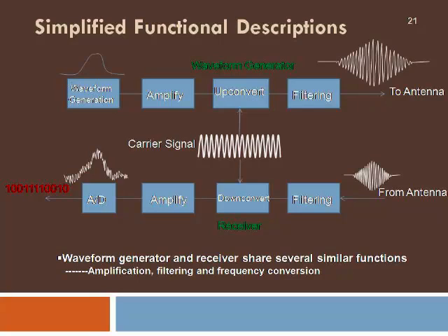So a carrier signal is separately generated for this, and after upconversion we take out the unwanted signals using filters. Then we are going to have the required pulse shape and also the required level of power within that. So it can be a simple CW signal or a pulsed signal or a Gaussian signal, or in the latest radars it can be an arbitrary waveform also. So this signal is going to be given to the antenna and it will be transmitted towards the expected target.